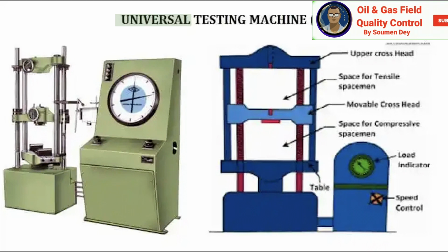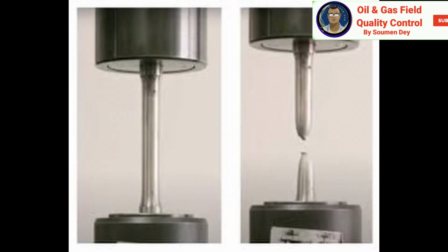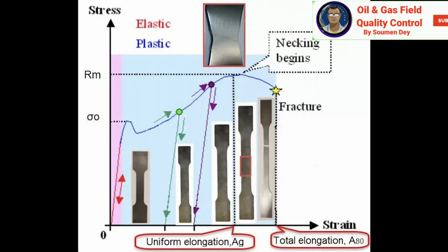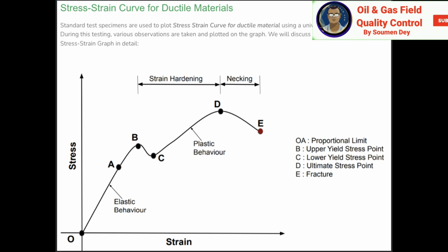During tensile testing, you need to record any change in length and the applied load on the test specimen at various time stamps until the test sample fractures. These values determine variation in stress acting on the test sample for each strain value. Afterward, we can plot the stress strain graph keeping mechanical stress values on the vertical axis and strain on the horizontal axis. Stress strain curve for ductile material.